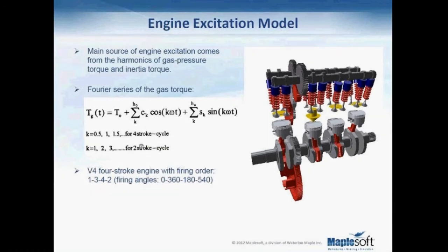In the industry, this can be done by measuring the cylinder gas pressures for different engine speeds and load conditions on an engine testbed using a pressure transducer embedded inside the combustion chamber.